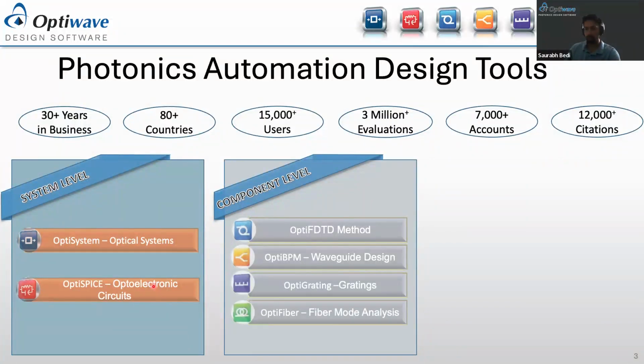We offer OptiFiber, which uses numerical mode solvers and other models specialized to fibers for calculating dispersion, losses, and birefringence during the propagation in fibers. Also, we offer OptiMode, which empowers users to thoroughly examine various waveguide structures, calculate supported modes, and determine key characteristics such as mode profiles and effective indices.